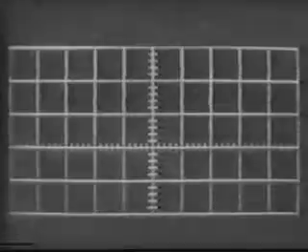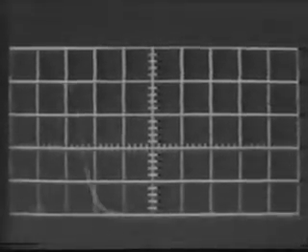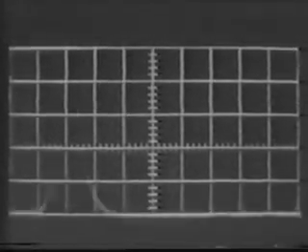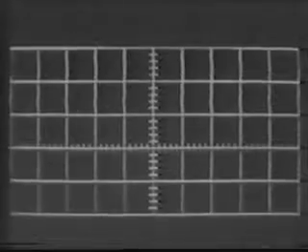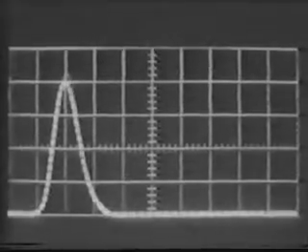The deflection is proportional to the concentration of holes under the detector point. Many other experiments show that such linearity is a property of a reverse biased detector rectifier. You will understand more about the reasons for this when you study p-n junctions. However, we can make a linearity check here. This pulse is now averaging 4 units high. The slight variations in height are due to slight variations in light flash intensity. Let me trace over one of these pulses, which is exactly 4 units high.